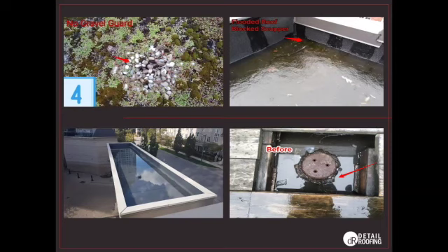In this particular case, we have the overflow drain here. A lot of times when we're looking at these drains during our maintenance assessments, we always want to check the membrane around, just because that can be splitting or cracking over time. If it wasn't properly installed and roofed in, then there can be openings there. And whether or not it's clogged and creating a flooding issue like this, water can be getting in at those open seams and creating an issue.